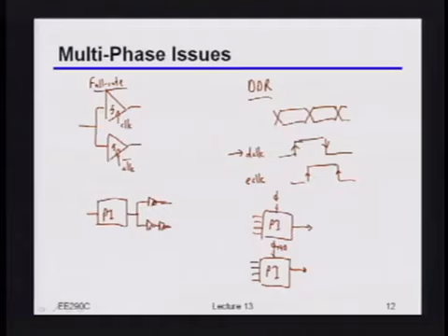Let's say even with a QDR kind of system, so quad data rate. How many phase interpolators would you need to support that? Yeah, you'd want 4 phase interpolators, right? If you have 8, you'd need 8 phase interpolators and so on and so forth. So first of all, what's the obvious thing that's kind of bad about that? Power and area. Yeah, power and area. Okay, and then the second one is?